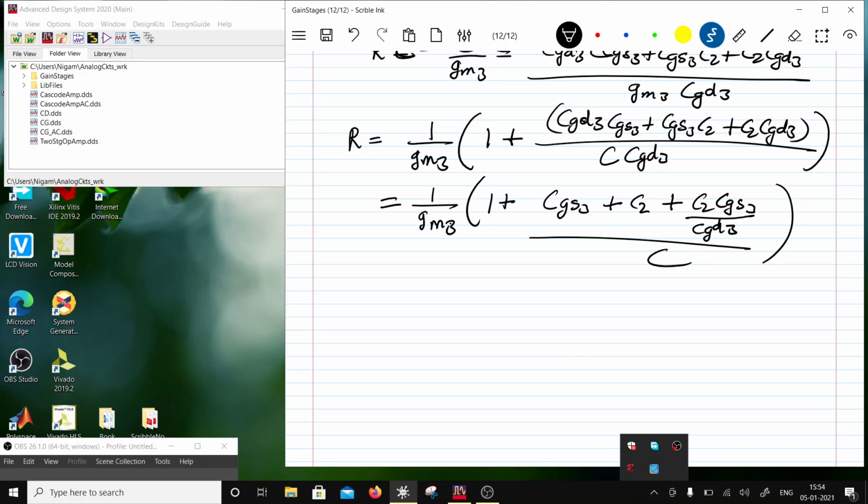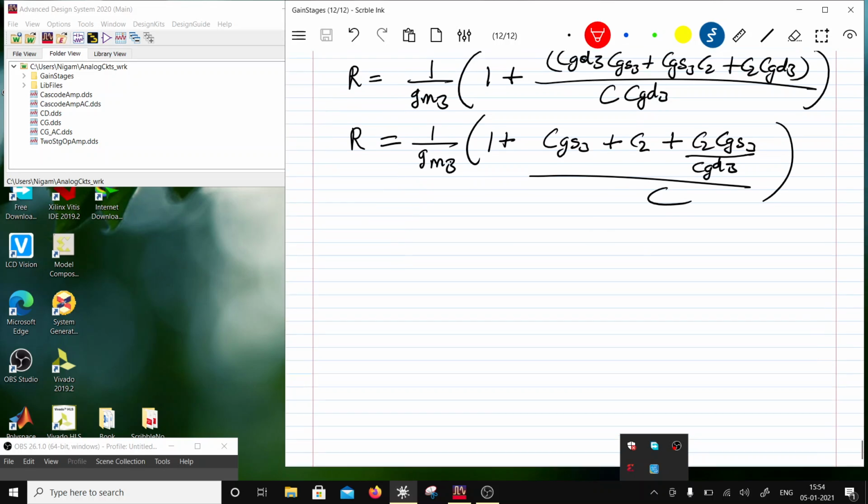Okay, so this is where your second pole will cancel out, and this is what I did when I kept on increasing R, right? I was first, so I cancel the, so I can move the 0 to infinity, and then I introduce it in the left hand side of the S plane and cancel the second pole. If I still keep increasing R, I'll be introducing the 0 between the first pole and second.